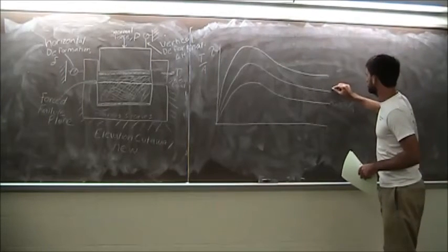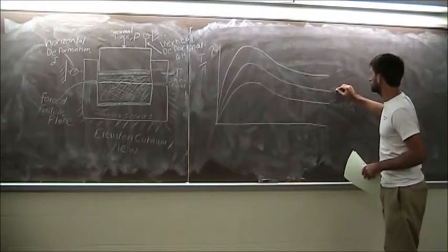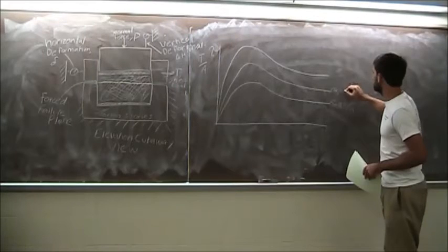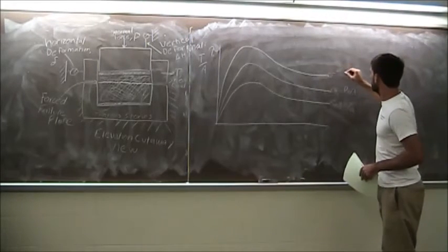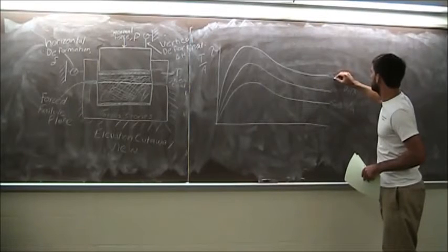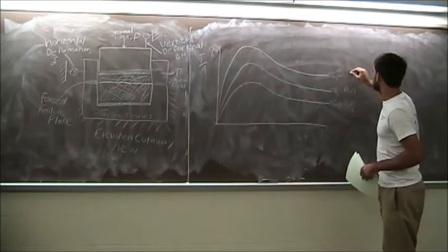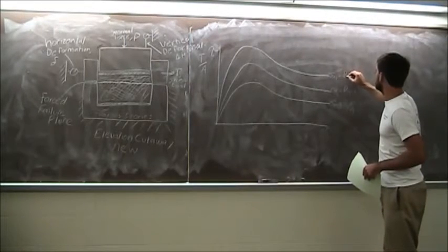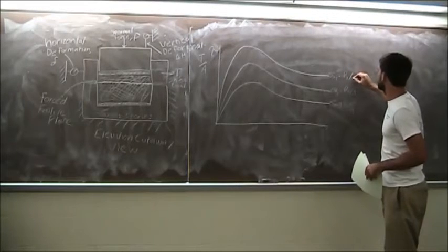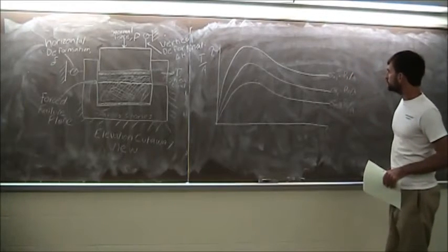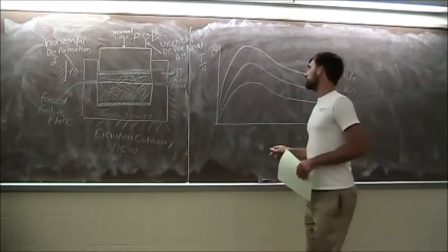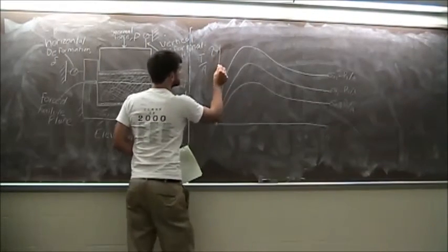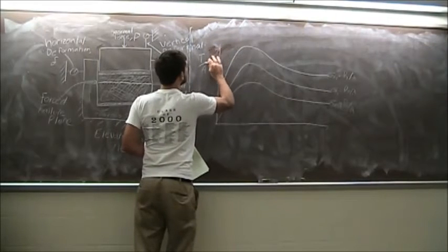And it's the same for the rest of these tests. Sigma n2 equals P2 over A, and sigma n3 equals P3 over A. Okay, so now that we have these values, I'm going to go ahead and plot these also over here.